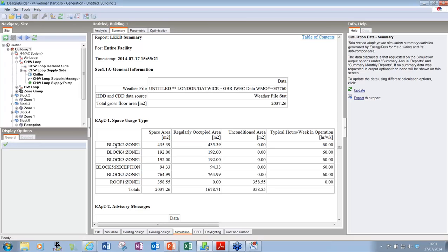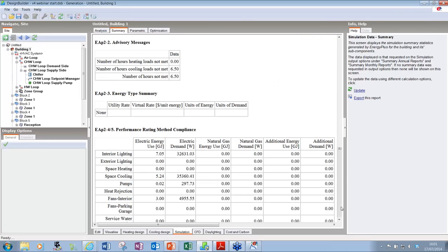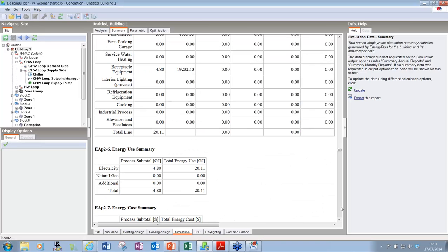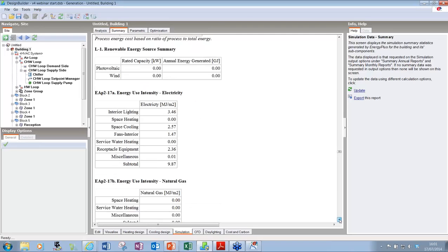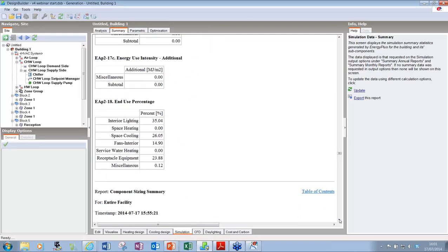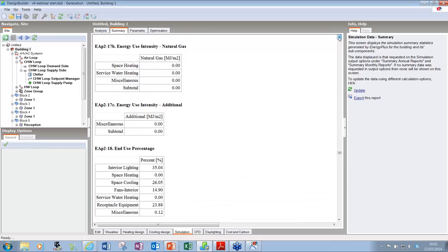Detailed HVAC systems are provided for all HVAC system types required for Appendix G baseline buildings. Once loaded, systems can be tailored as required to meet particular requirements of your building, for example, adding multiple chillers for large buildings.